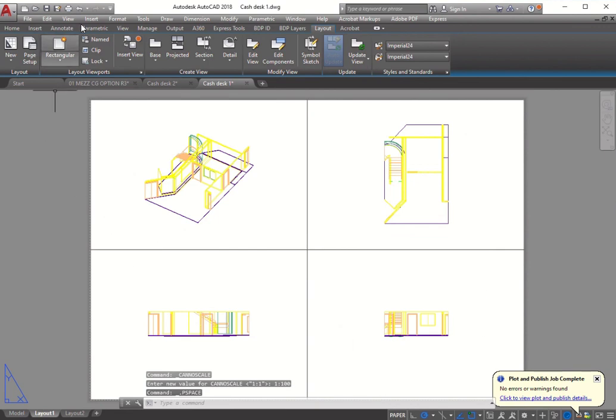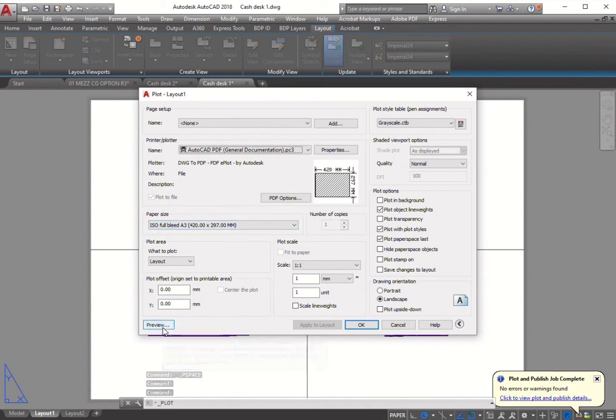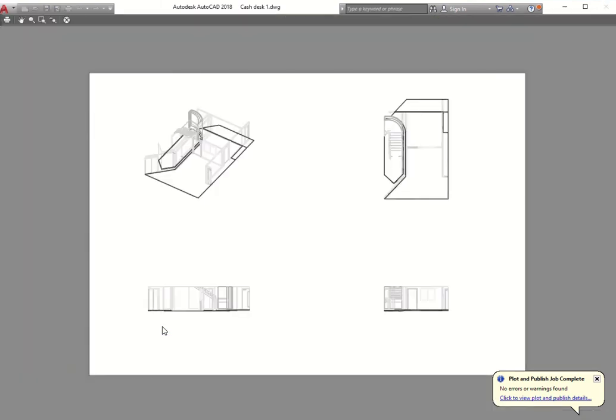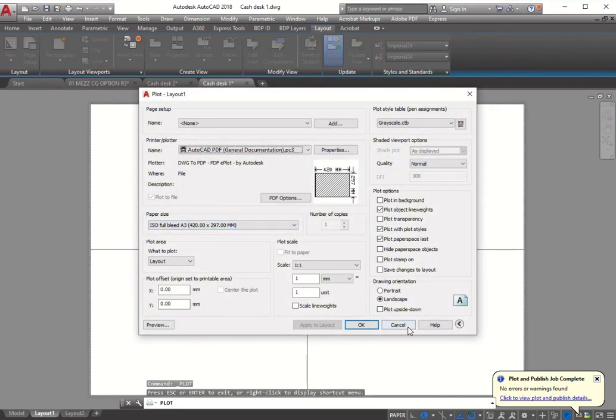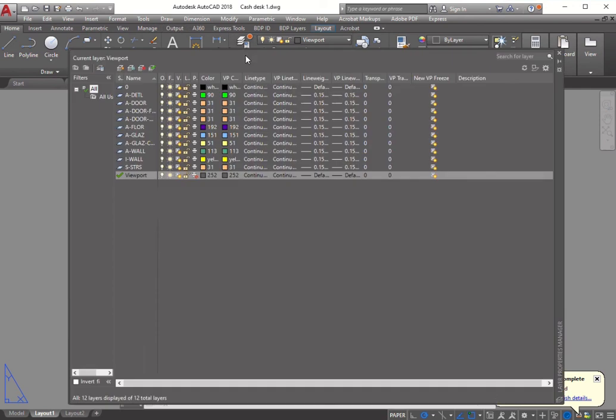Now, let's go to the print and preview this time just to make sure that everything's correct. This time, maybe you want some lines in between, so to frame out these drawings. So if I go back, so cancel, and so go to the Home tab, and then Layer Properties, and then within here, just deselect that so the frame of the viewport will print.